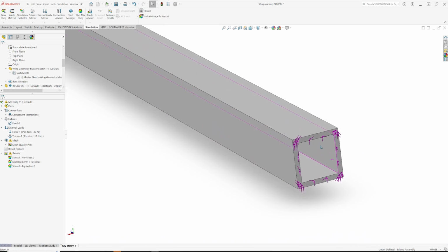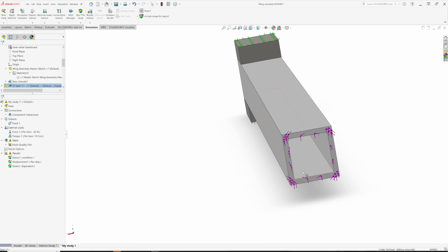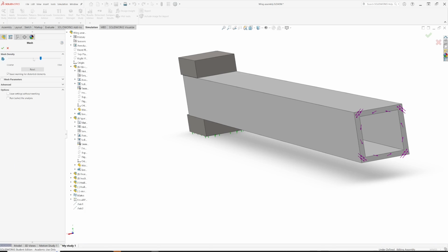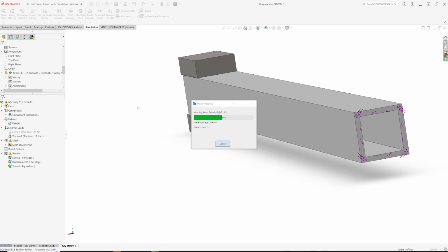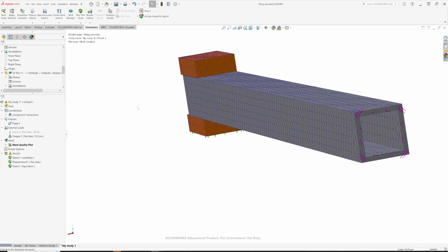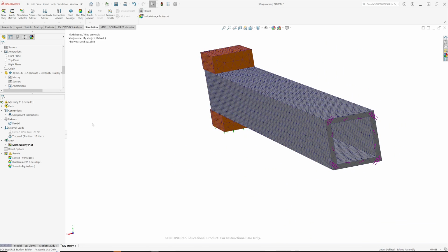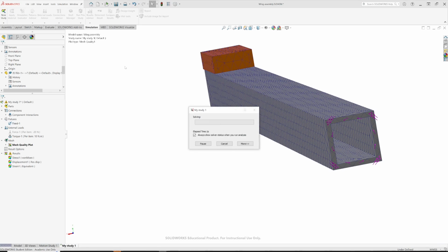If you've done it right, you should see these kind of magenta arrows flowing round in a circle around the end of the beam, that shows that you're applying a torque around there. If you've done it wrong, these arrows might be pointing in random directions. That's what it should look like. Press that. So turn off the force. We suppress the force. Okay, and our mesh, wind that back a little bit. Just makes it run faster. That's more than enough points to make it run. Okay, everything else is the same, so let's run that.